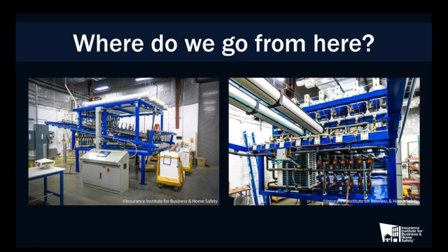It was geared... We haven't talked much about full-scale testing, but if you know a little bit about the IBHS Research Center, we do have a very, very large full-scale test facility, and we can do full-scale hail simulations in that. So we needed to produce a large amount of laboratory hailstones as well as consistency amongst those laboratory hailstones for repetitive testing. And we talked a little bit about the variability in the FM standard ice ball versus some improved testing. And so what we've ended up with is this system.